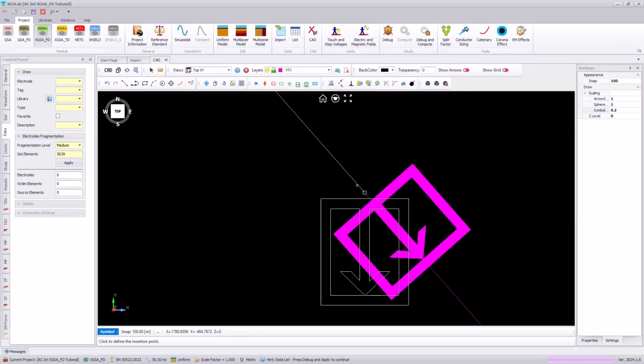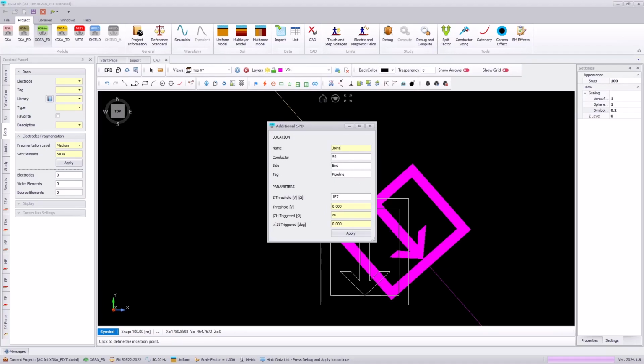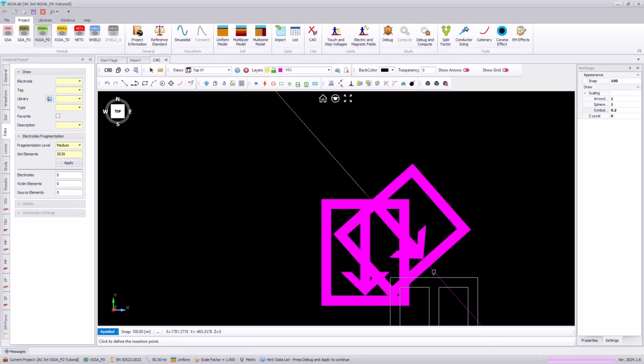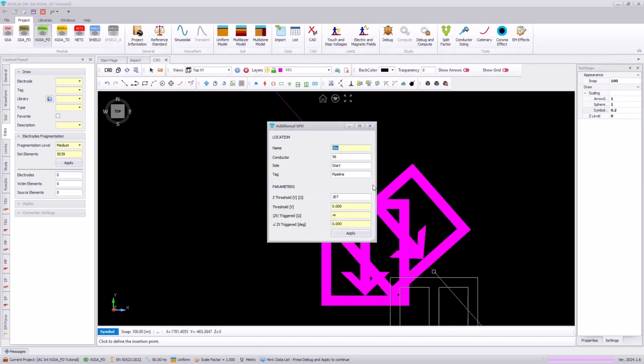And we will now insert a transverse impedance. This will be joint B up. And following the tutorial documentation, we are going to use the 70 volt threshold, but now a 5 ohm impedance once triggered. And we'll do the same thing down below this joint.